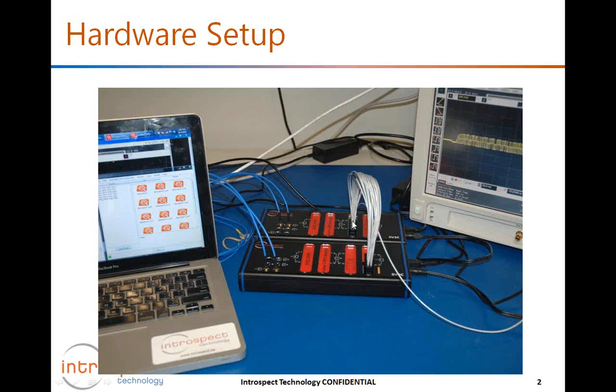What the generator also has is an extra resource called a replica channel generator, and that's the extra wire that we show here going all the way to the oscilloscope. So whatever the generator is doing to the receiver, whether it's the Introspect receiver itself or any piece of silicon, we have an extra resource where we could view the actual functional pattern that's being produced on an external instrument like an oscilloscope. And everything is controlled with the ESP software that's shown on the left-hand side here.